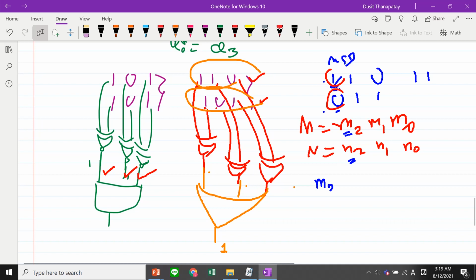So you can write down M and N prime for the bit. Okay. If M2 is 1 and N2 is 0, this condition becomes true. M is greater than N, right? Or if M2 and N2 are equal, namely M2 XNOR N2 is true, then you must check, right?